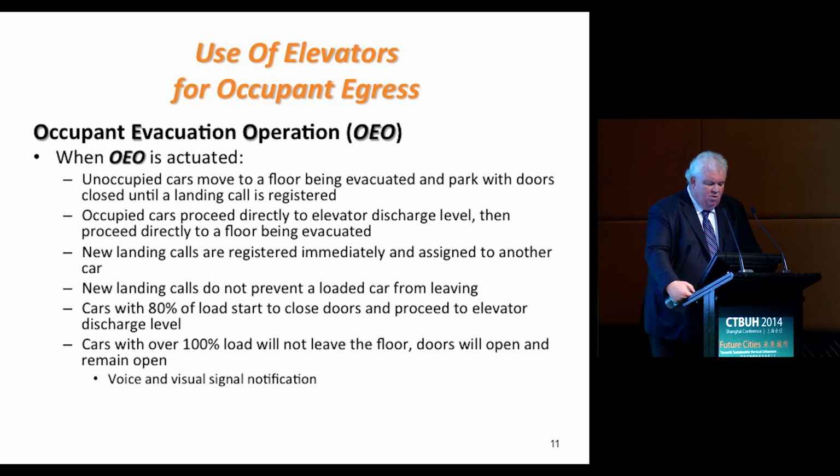Unoccupied elevators would move to a floor being evacuated and park with the doors closed until a landing call is registered. Occupied cars would proceed directly to the elevator discharge level, then proceed directly to a floor being evacuated. New landing calls would be registered immediately and assigned to another car, and any new landing calls would not prevent a loaded car from leaving.